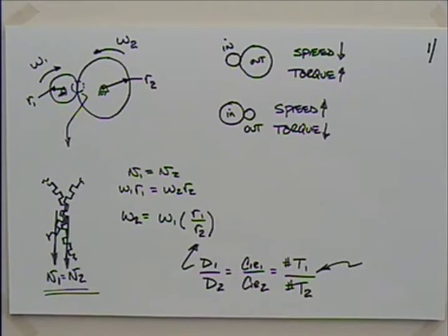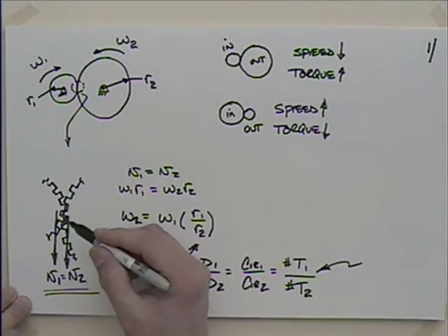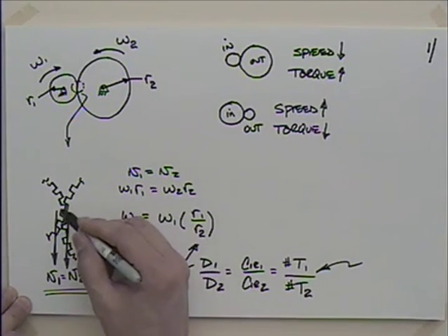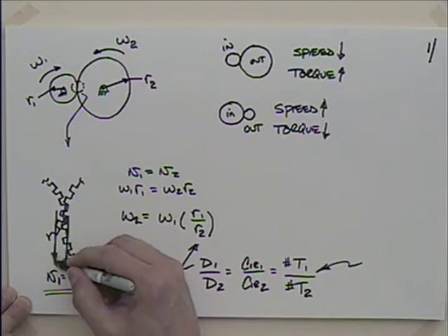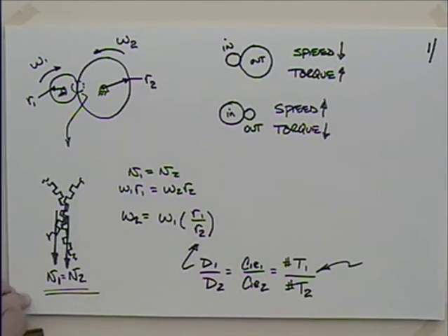That's a great exercise in this, because they're trying to make the gear velocities match each other. If you want to go from second gear to third gear, if you can get the gears going the same speed, get this speed here and that speed there together, you can just slide the gears across one another and right into place.